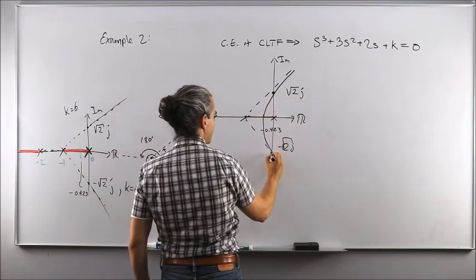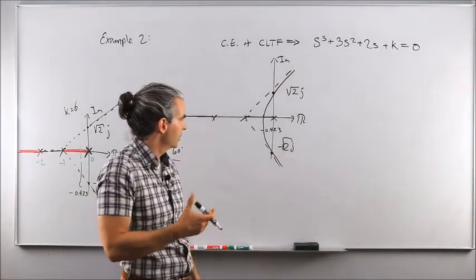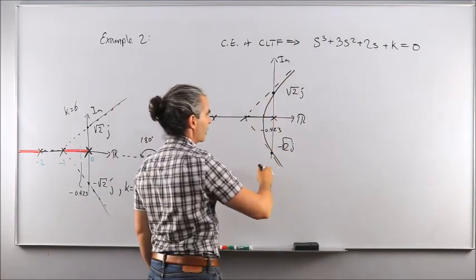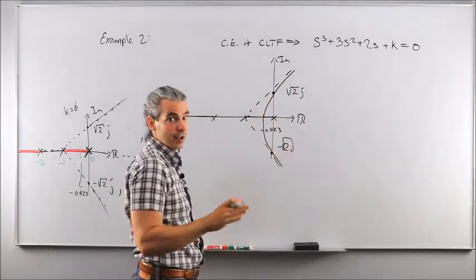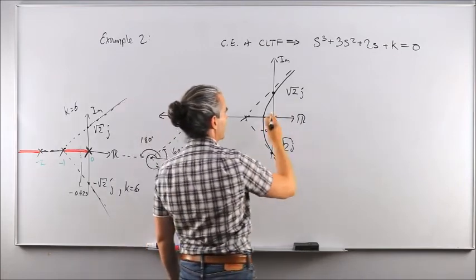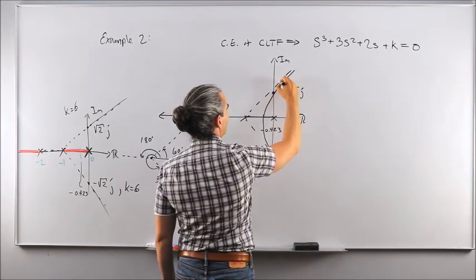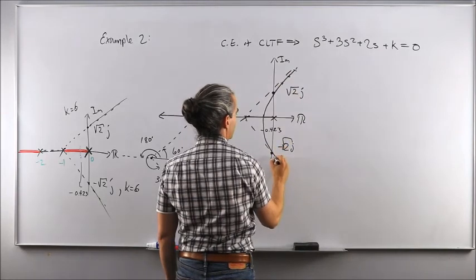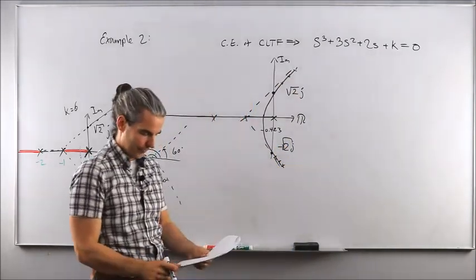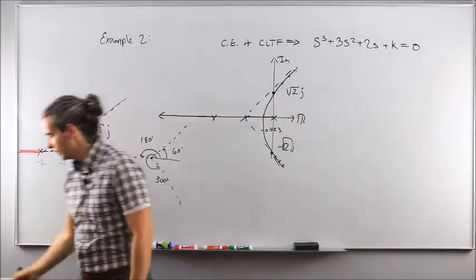Whenever k is equal to 6, I would say that this is your limit to remain in the asymptotically stable region, because at k equal to 6 exactly, you get marginal stability or sustained oscillations. It's not asymptotically stable, as per past discussions. And whenever k gets larger than 6, that means your poles are now in the right-hand side of the complex plane, and the whole closed loop system is now totally unstable. Okay? I hope that makes sense to you.